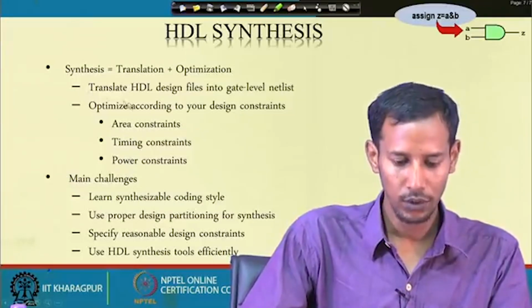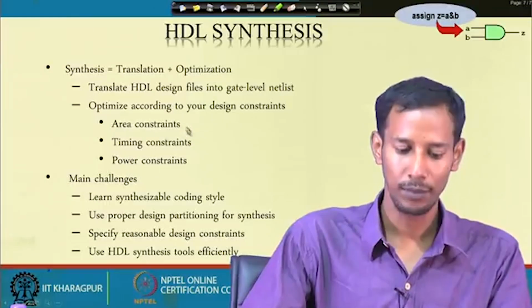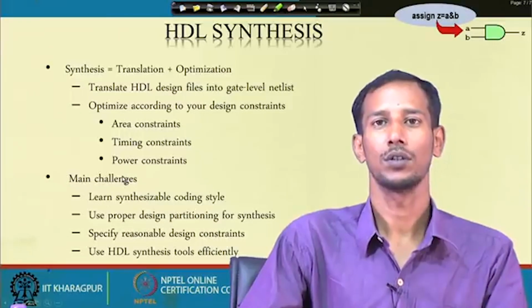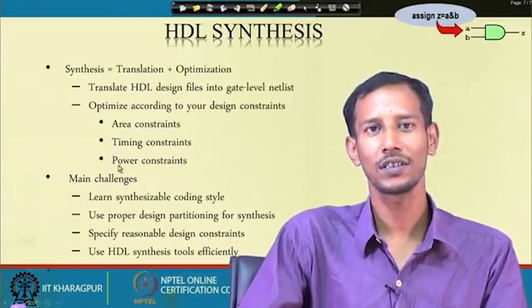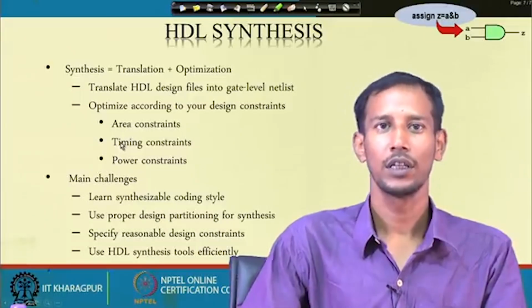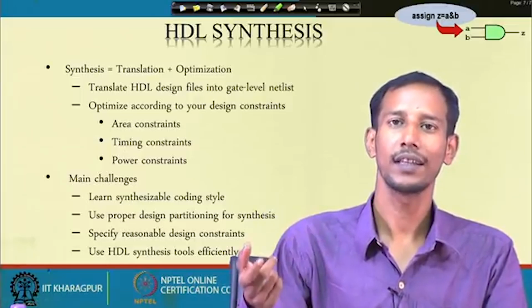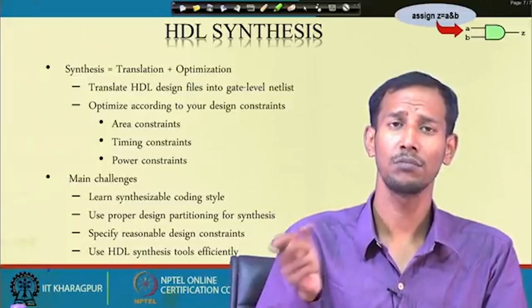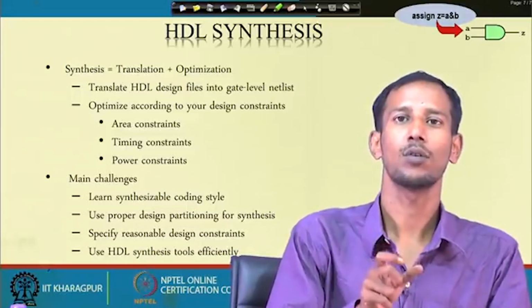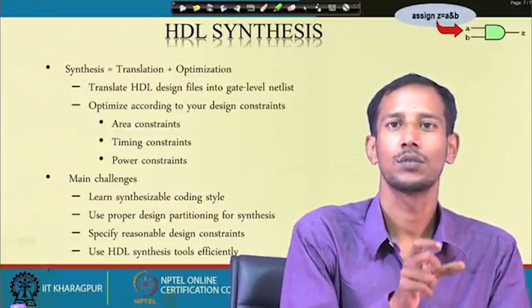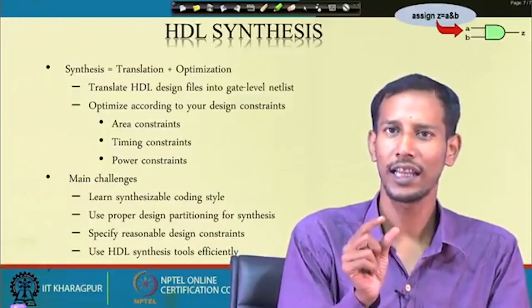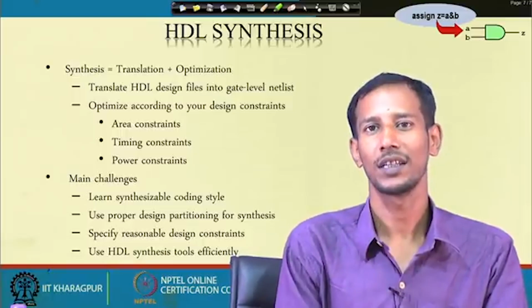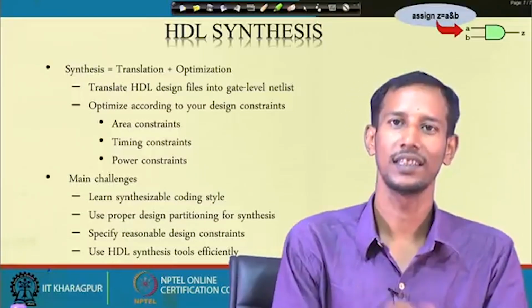So, that is why whenever you are optimizing your design, at that time you can put some constraints, such as area constraint, timing constraint and power constraint. So, where will we get the information about these constraints from? From the specification you will get this information. From the specification, I already know that my targeted clock speed is 1 gigahertz. That means the maximum clock time required, 1 nanosecond, I have to achieve whenever I am designing the system.